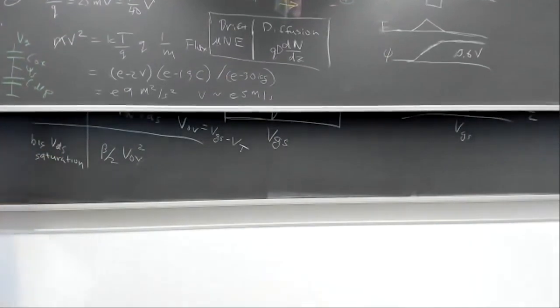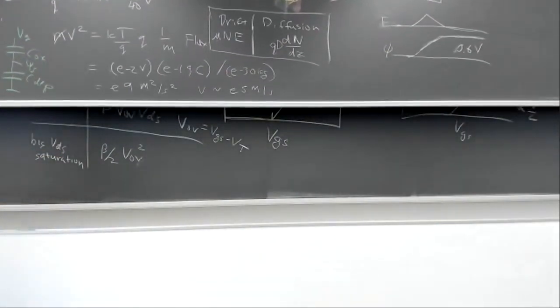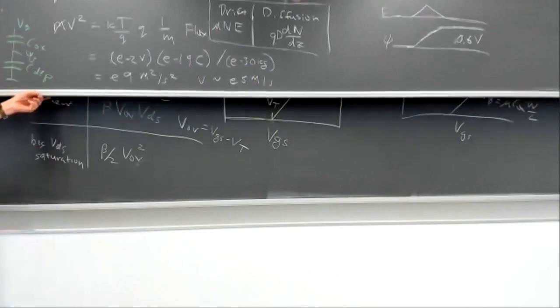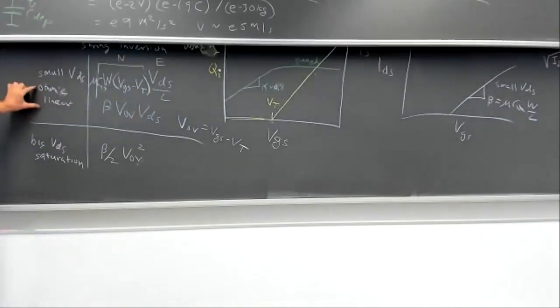So the surface potential is uniform along the channel? Yeah, under these conditions, that's a very good question. Do we assume a constant charge density in the channel? Yes, because there's only a very small electric field across the channel, so the charge density is constant. It's just a uniform sheet of charge. Yeah, under these conditions, a small VDS, under the ohmic or linear region.